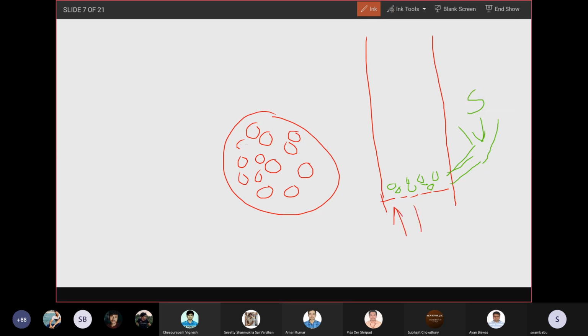So when you blow air with high velocities, usually velocities greater than 20 meters per second, but this depends upon the size of the particle. If the particles are very, very small, you don't have to go for 20 meters per second. If it's micron size particles like 50 micron or something, definitely we need velocities of 20 meters per second.